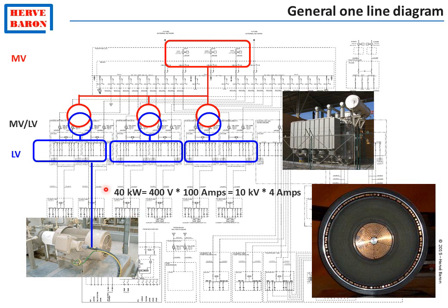This means that the power supply cable carries a high current and therefore has a high cross-section. The same power, if carried at a higher voltage, would require a cable with a much smaller cross-section, as the current would be much lower, and the cable cross-section is determined by the current.